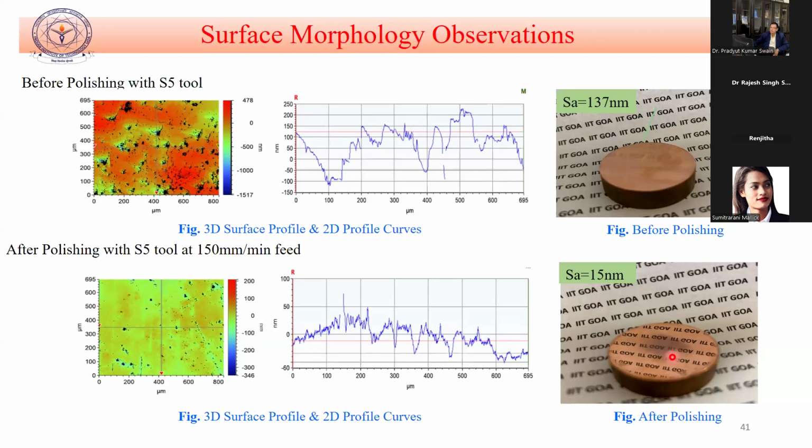That means whatever material is removed from the workpiece surface should be accommodated on this abrasive tool, just like in grinding. In grinding, there is a porous structure. If you see it in a high resolution microscope, the grinding wheel looks very hard and rigid, and that is true, but the structure is porous. Then the next aim is that we obtain our flexible abrasive tool, a flexible grinding wheel, and that we make it porous.